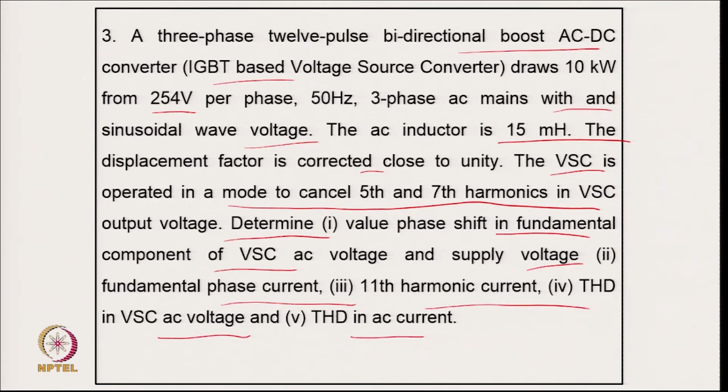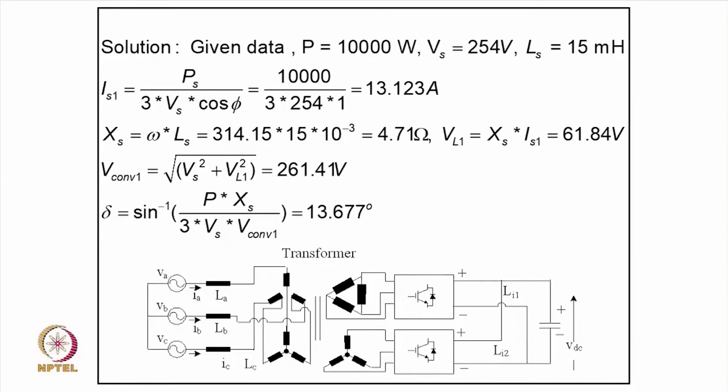So, what we have here is typically a 12 pulse converter, and the difference here is that on the grid side we are connecting the transformers in series, and on the load side we are connecting them in parallel, because we want to apply the same DC link voltage. So, we are using 2 voltage source converters. We can of course either feed the load here, or we can have solar injection, or bidirectional power flow in this voltage source converter.